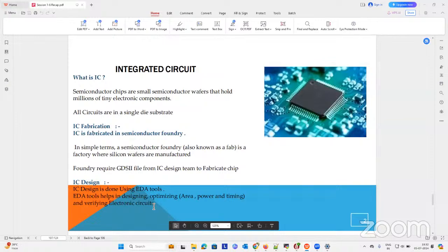So what we have done is write Verilog code, and for verification we wrote a test bench and checked the design functionality. Using synthesis, we verified the netlist, and reported area, power, and timing. The Cadence tools we are learning are very advanced. They have included artificial intelligence and machine learning in the tools also.